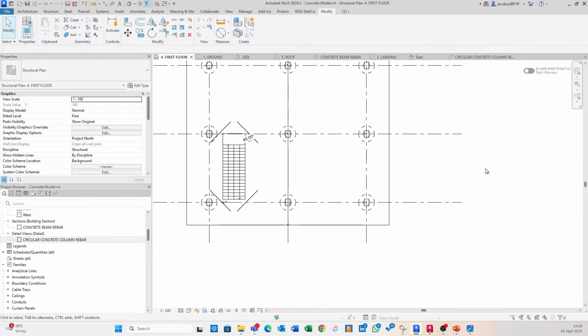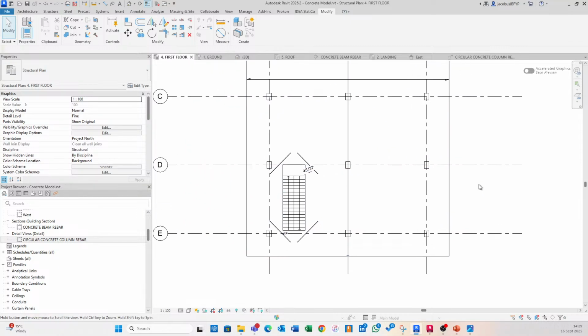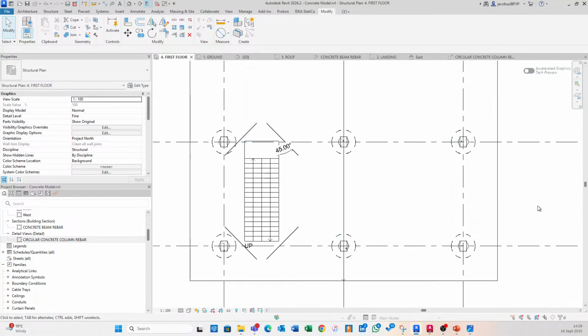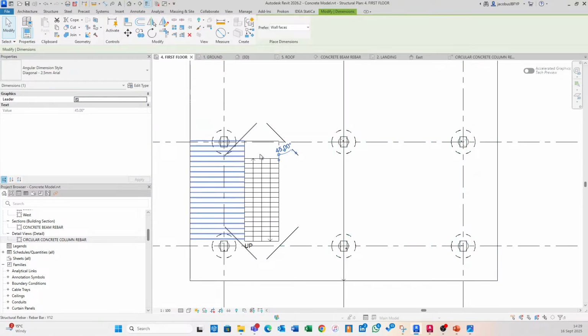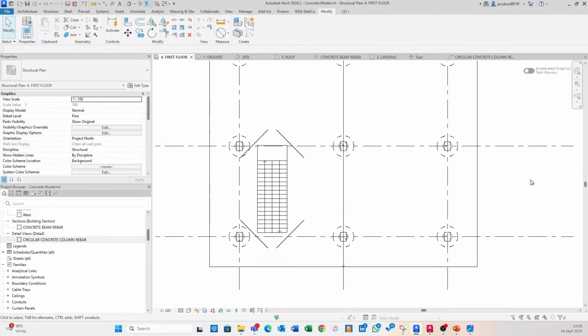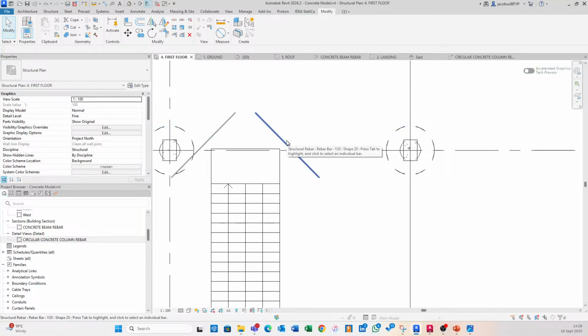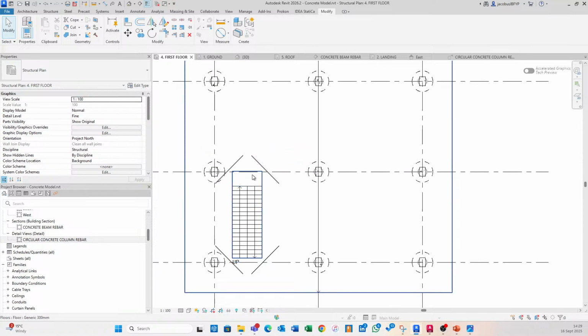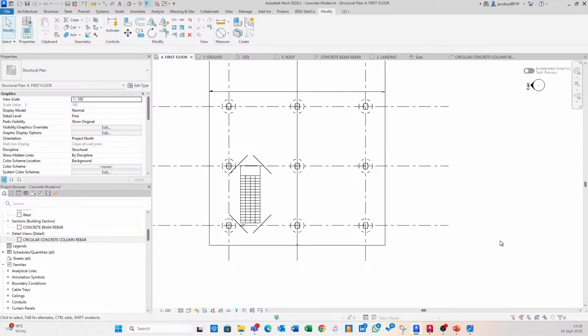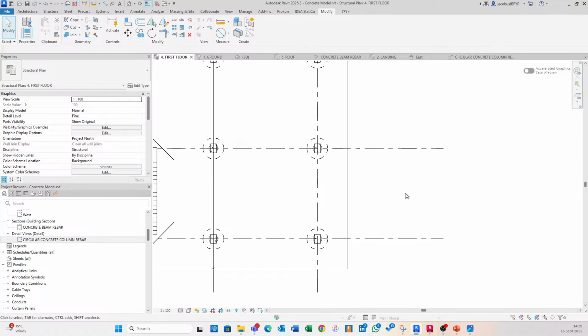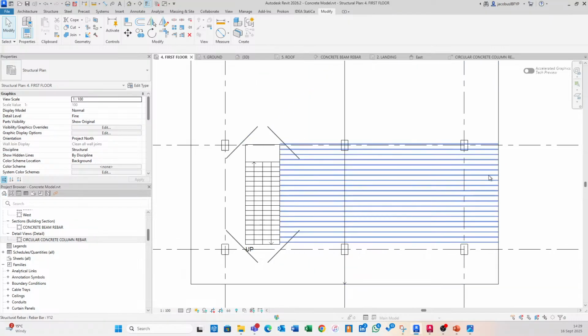All right, and I can do the same. If I cut through the slab, I can mirror them top and bottom as well. And that's our diamond bars, right? Those are the sort of things we're interested in. You can then either go and you can delete this dimension. So if we delete it, the bars will still stay there, and then we can use things like copy functions to create doubles. So it's good to actually create the first one, get all of the top and bottoms done, get their spacing correct, and then to actually mirror them along all the sides. That's really useful. So the mirror functions work, your dimensions work. So really, really useful actually that these rebar elements behave like most other structural elements.